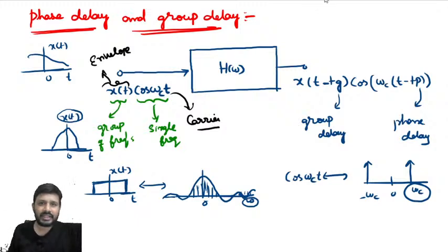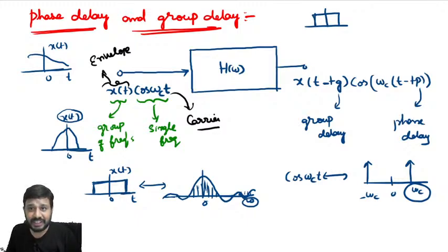The point here is, you must understand, if anybody asks you how many frequencies are there in this kind of signal, you must say an infinite number of frequencies are there, and they are in equilibrium such that we get this kind of shape. If you change or disturb the equilibrium, this shape will be disturbed. Suppose I disturb the high frequency components, the shape will become like this. High frequency components are responsible for sharpness. If I remove the high frequency components, the pulse gets smoothened like this. Remember, this much concept is there.